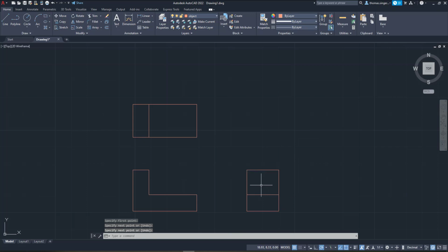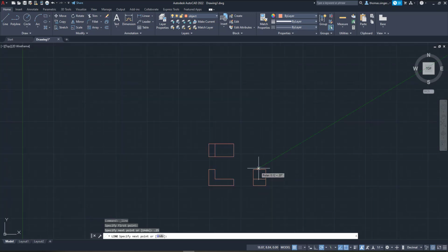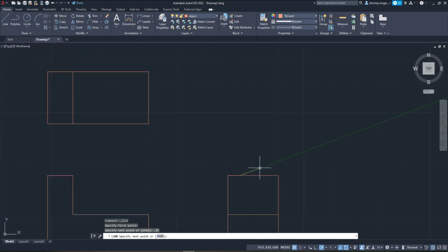Now, we have a cutout here in the middle that we need to work on. And it's a 1/4 inch, okay? And so I wanted to show you how to do this. And we're actually going to draw over the other line. So we're going to point straight across 0.25. And the distance down is a 1/2 inch.